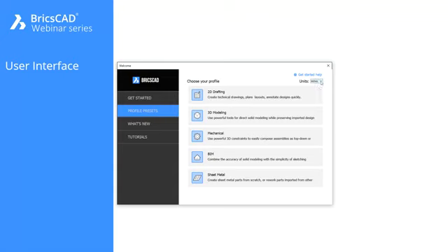Okay, so also the other thing you want to be aware of is up here in the upper right corner where you can specify the units. And I'm here in the US, so I will choose inches. Then I'll select a profile. If I typically do a lot of 2D drafting, then that might be the profile I want to start with. You can take the default name or you can give it some other name. I'll just say HH just to distinguish this as a profile that I'm creating based off that template.